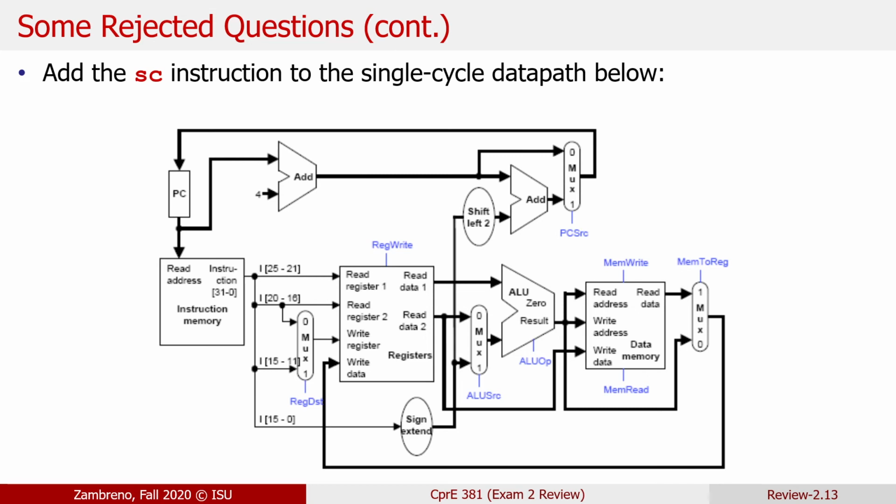And that's the right thought process. I'll reiterate that if I were to ask this on the exam, I had better do a better job of explaining exactly what the instruction does. If it was a store into a memory, then there's definitely some muxes needed here because normally there is no path that takes a constant, takes the immediate, and connects it to memory. We would just have to add that path, right?